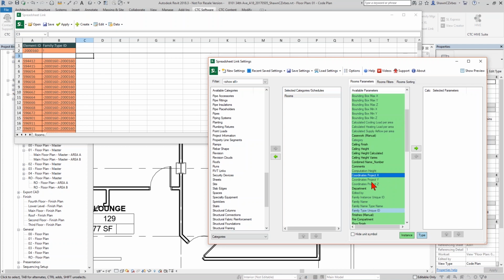There's also the actual coordinates of the element, the placement point of the rooms. This is true for any element that you pick. So if you want to know exact placement points for, say, column components, you can know the placement point for that. There's other things you can grab. Position is another good one to use. There's a lot of values that normally Revit just doesn't show you that you can pull from here and do something with. What I'm going to do is grab something like level.